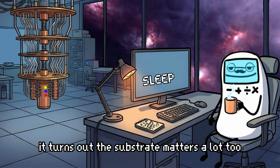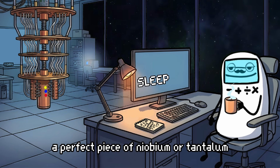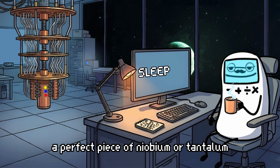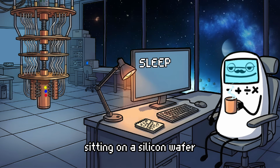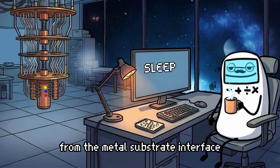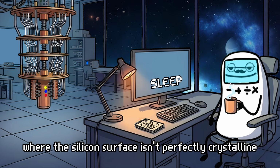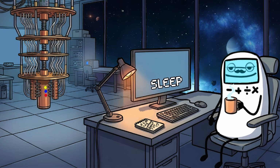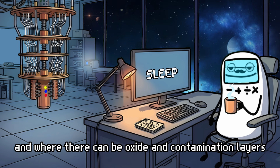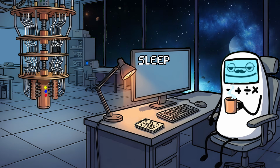It turns out the substrate matters a lot too, not just the metal. Even a perfect piece of niobium or tantalum sitting on a silicon wafer will have loss contributions from the metal-substrate interface, where the silicon surface isn't perfectly crystalline and where there can be oxide and contamination layers.